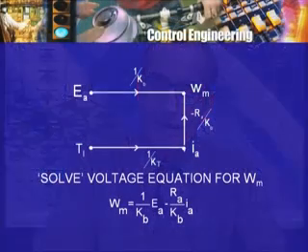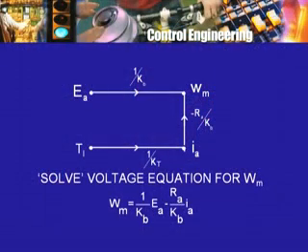So then what do we get? We get IA equal to TL divided by KT. So here is one more edge going from TL to IA with a transmittance of 1 by KT, and we have another contribution which is KF into omega m divided by KT. So here will be an arrow that goes from omega m to IA with a transmittance of KF divided by KT. So this is another signal flow graph which is equally correct for the two equations, in which now EA and TL are the input nodes, omega m and IA are not input nodes because they have incoming arrows.